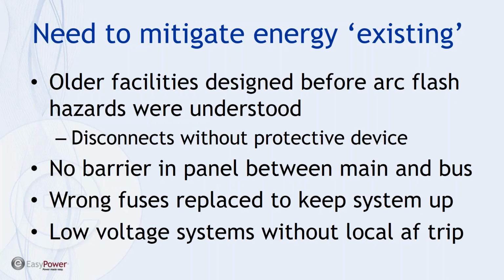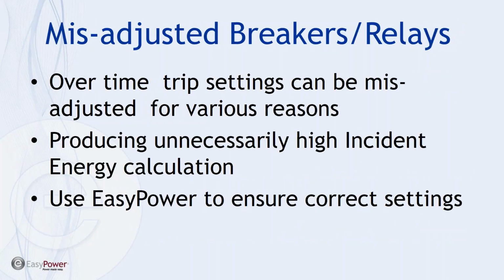Another area where there are easily defined considerations is in low voltage systems, actually 250 volts or less, where we've identified incident energy that's reported as elevated in an arc flash study utilizing the IEEE model. And that's a little different discussion, but the tools again let us visualize that as we get in and look at the one-line diagram.